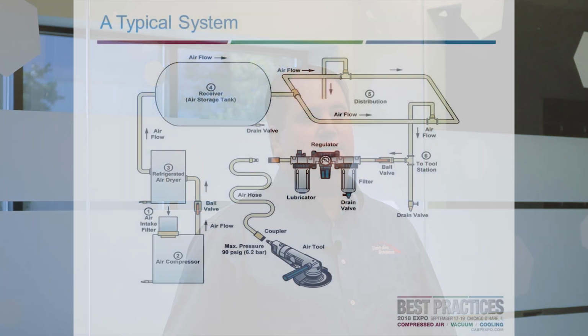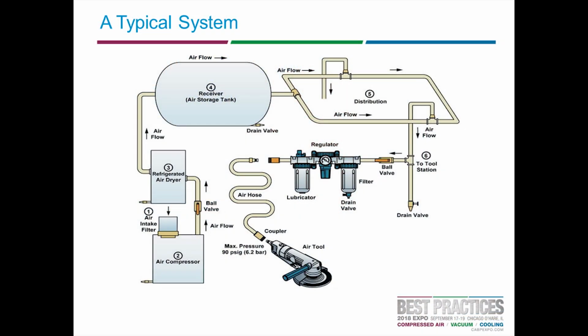This slide here is the overview of a typical compressed air system. Each of our compressor rooms include some type of compressor, maybe multiple versions of, and some type of filtration package, including a refrigerator dryer, maybe a desiccant dryer with pre and post filtration. We may have a wet receiver before that filtration, but typically we don't see that in smaller compressed air systems. And then as we leave the compressed air filtration zone, we go into our dry tank and then feed out to the header network system.